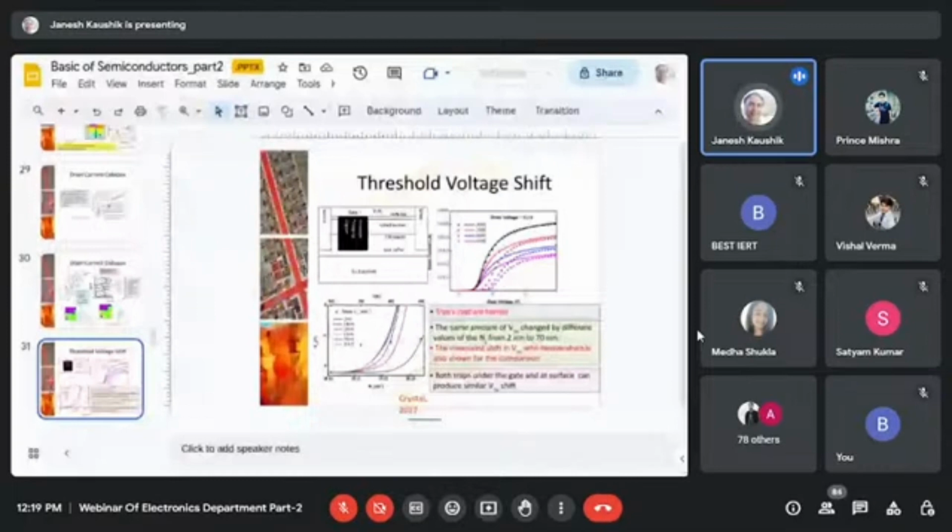So these are the DLTS results of the different aluminum gallium nitride HEMTs. That diagram which I have shown, in DLTS measurement we get a peak in the capacitance difference, and this is the practical data. We get the different peaks, and the shifting of these peaks with temperature gives us the activation energy, and we calculate the DLTS peak from the leakage current also,